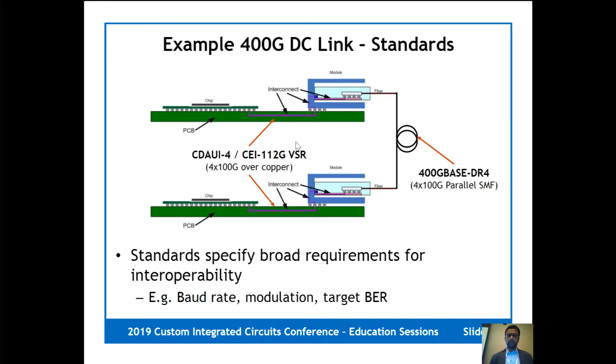And in that case, we would design the SerDes both on the host side and the line side to conform to the CEI 112 gig VSR, or very short reach link. So in the subsequent slides, we look in more detail at what these standards entail, but here I just want to introduce the terminology and what standards relate to which portions of the link.